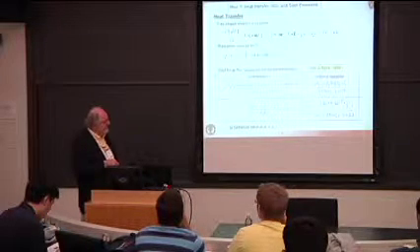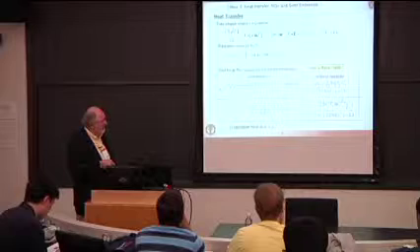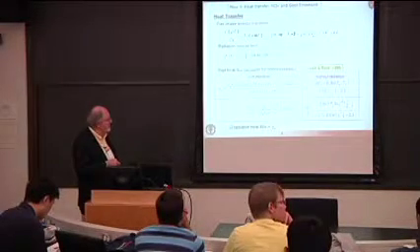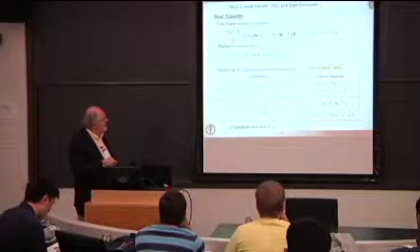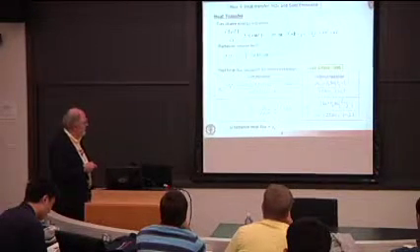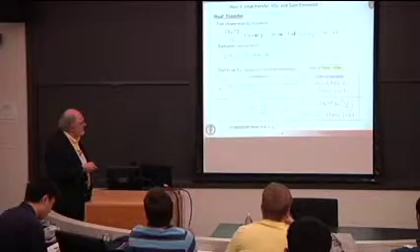Looks very much like the log law of the wall, except in the log law of the wall, this is not a logarithm, it's a linear difference in temperature. Now, if you include other contributions to the wall heat flux, you get this extra term here.